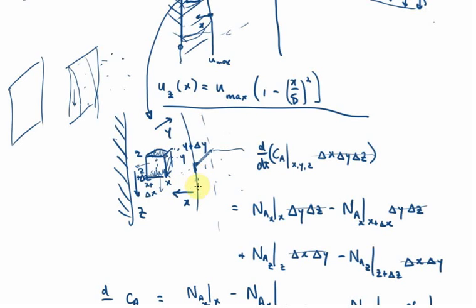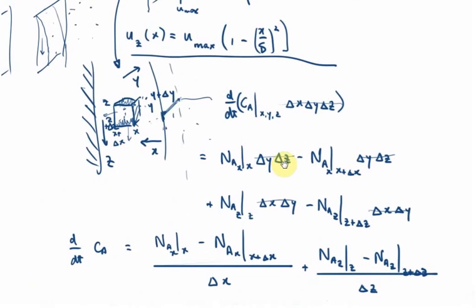Remember, when we are writing the boundary conditions, we are writing that over this particular phase. So we've written a balance on the liquid film. So talking about the gas out here doesn't complete the picture. We need the boundary condition in the film. So even if we happen to know this value here, we still need to translate that into a liquid concentration value. So let's say that we do happen to have the gas phase value here.